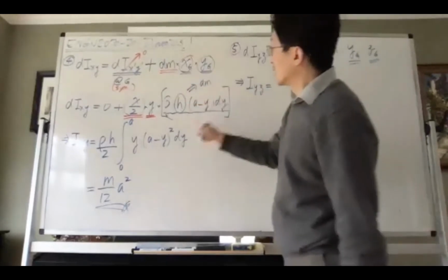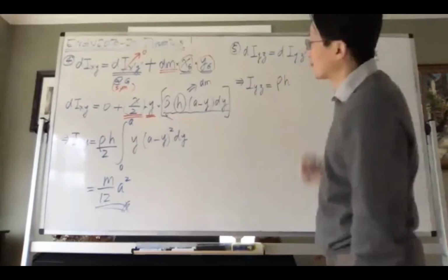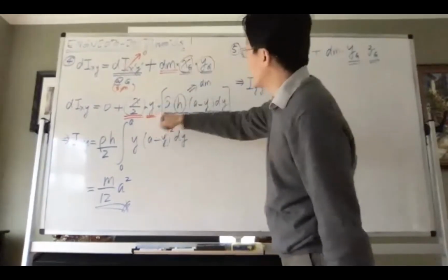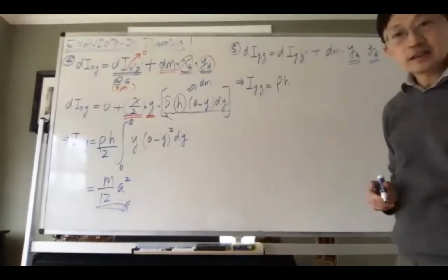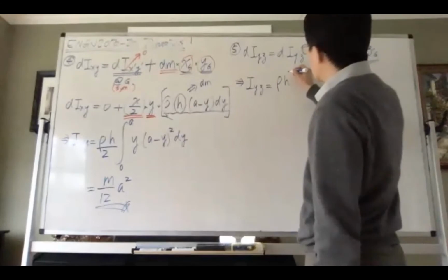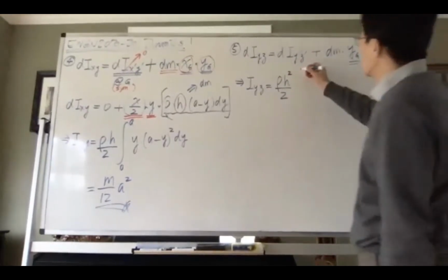So in this integral, you also have rho and h, take it out, because they are constants. And for yG is y. What about the zG? zG is h over 2. Take it out because it's constant. So that makes this to be h squared over 2. And then you integrate the rest.